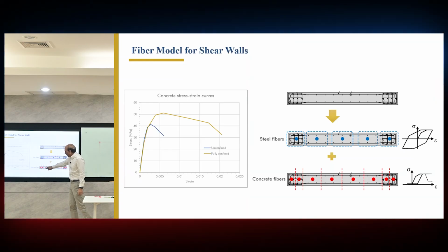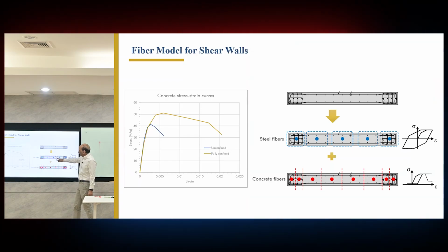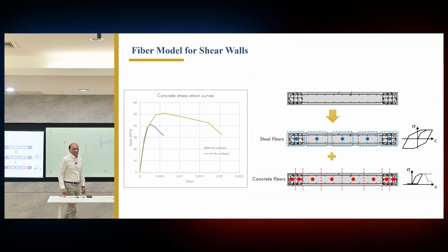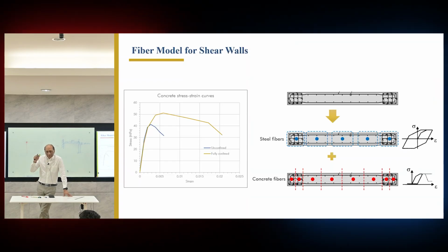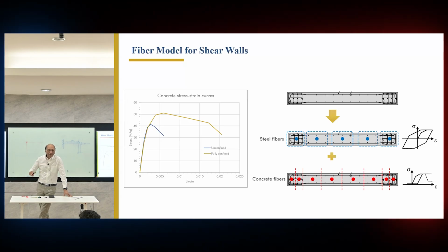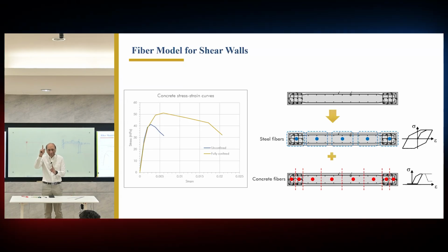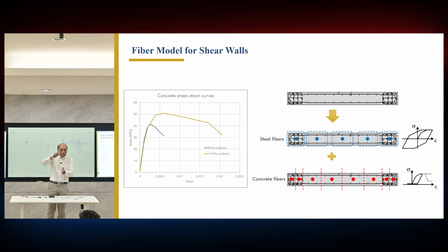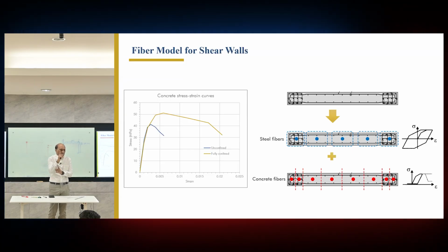So this whole section will be one fiber, one fiber, one fiber. A few fibers are identified as concrete and steel, and based on that, the corresponding materials are assigned, and then you get the curve. So it's just a very rough meshing so that you can quickly generate the required behavior. Each fiber is vertically connected, and they deform together as a big cross section.